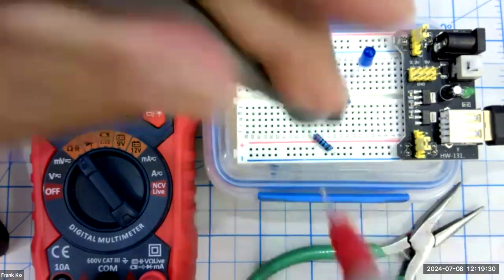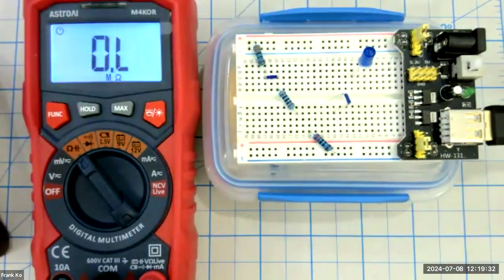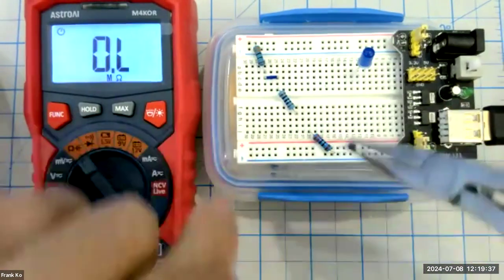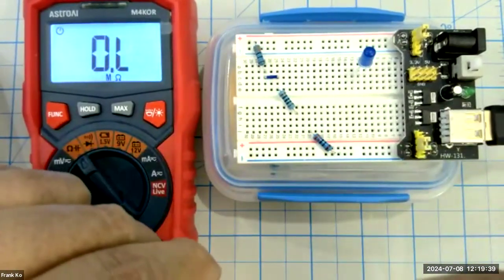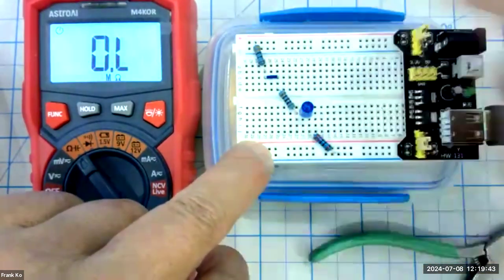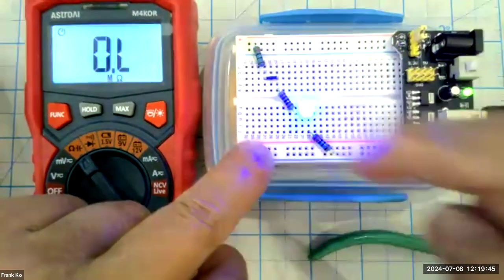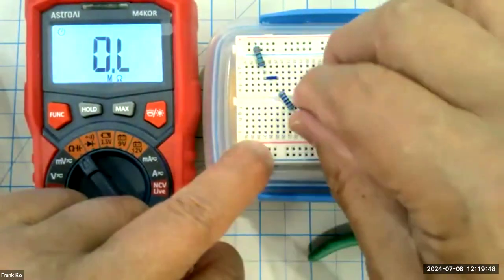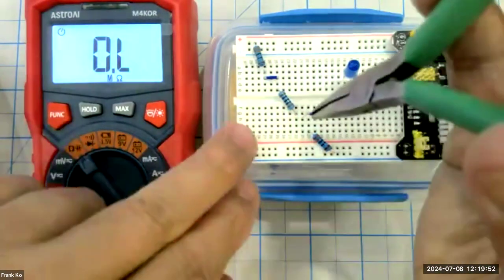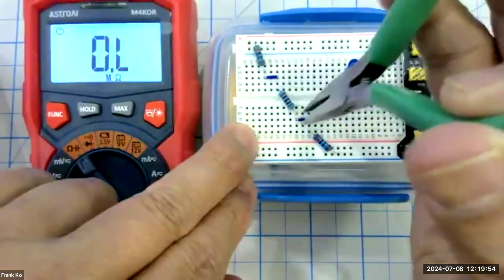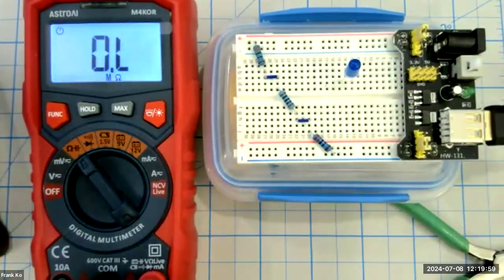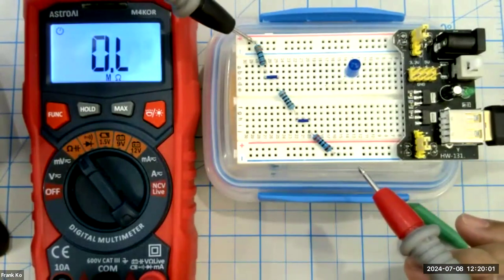Okay, now if we want to measure total resistance, here's something interesting that I said would be a problem, and that is if I put the jumper back in place of the LED. Let me just go ahead and pop this right back here so you can see, yes, light it up. It's on, circuit flows, current. This is wonderful. Put the LED out, and let's go ahead and grab this little jumper, put it back in, like so. And if you go to measure total resistance now, we're not going to measure the 650 ohms.